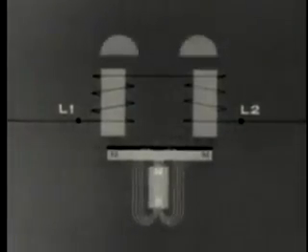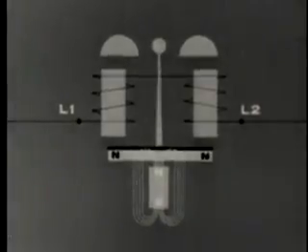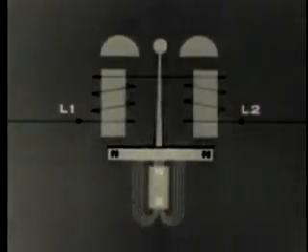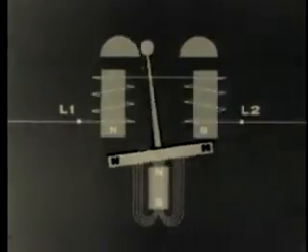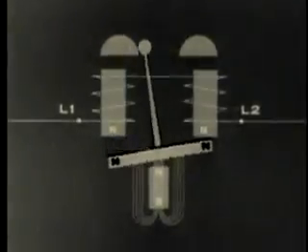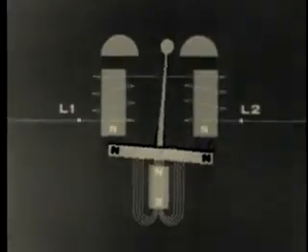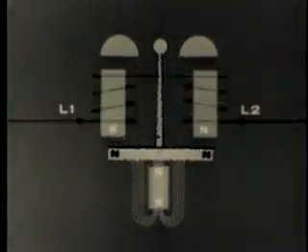If we introduce a soft iron armature near the base of an electromagnet, and then introduce a permanent magnet to polarize the ends of the armature, an unstable condition will exist when current flows. When a signal is sent over our line, the polarity of our electromagnet will alternately attract and repel the ends of the armature, operating the clapper rod, which alternately strikes each gong. Here we see an actual telephone ringer in operation.